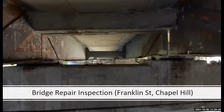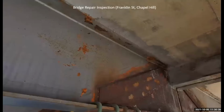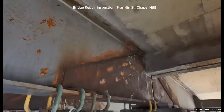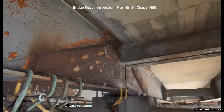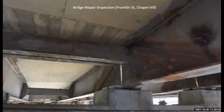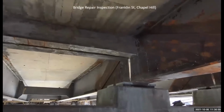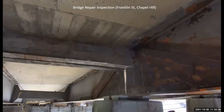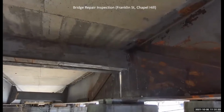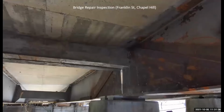We had a project in Chapel Hill this past year that was a bridge rehab project, and the drone allowed inspection of the repairs without having to have an employee on scaffolding or using a man lift. This is a video of where a drone was able to go up in between the girders and do some inspection that was a lot safer and easier than putting a man up there. This was a special drone, I believe mentioned earlier in this presentation, the SkyDio, which has crash avoidance sensors on it. As you can see, you can get real close to the girders and see if the repairs that were made were substantial or if they were accurate.